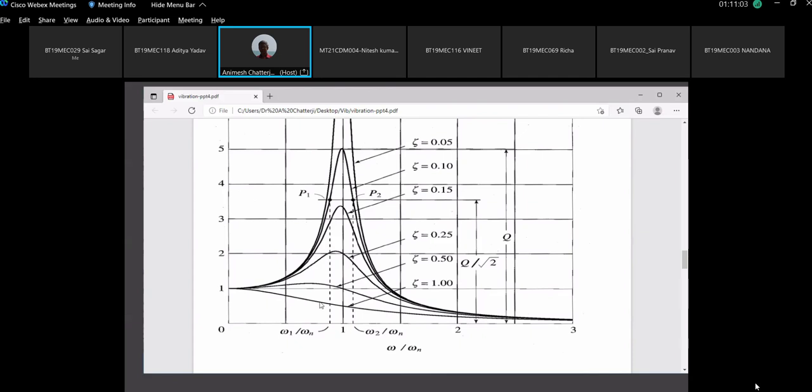Generally, we do not talk about that much of damping. Why? Natural damping never goes that high. Even in a suspension system, we don't push that much damping. So mathematically, we generally don't discuss when the damping factor is larger than 0.707 in forced vibration. So we assume that our system has a damping which is much less. So our graph will look something like this.